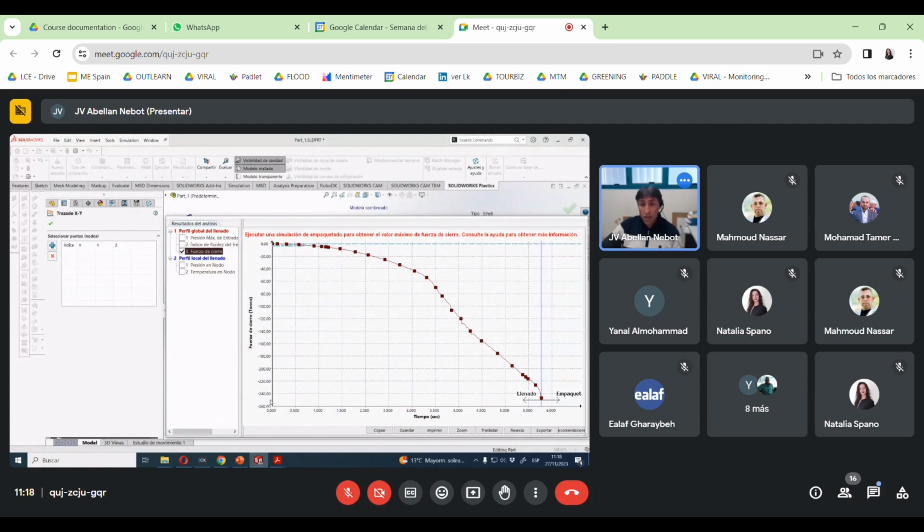So this is a lot. You remember the Chinese machines that we reviewed had a clamping force of around 100 tons. So this part is quite big, and the clamping force at the end is quite large. We need to create a clamping force of 250 tons.